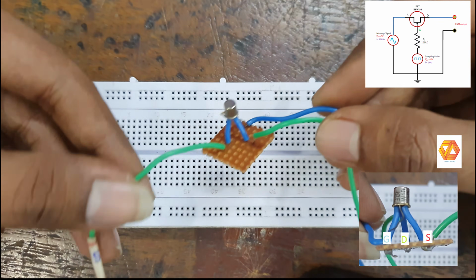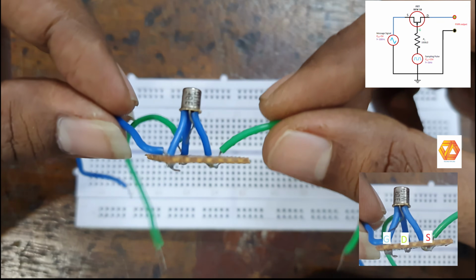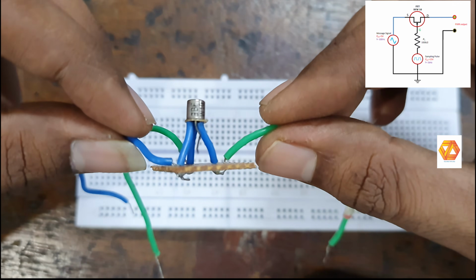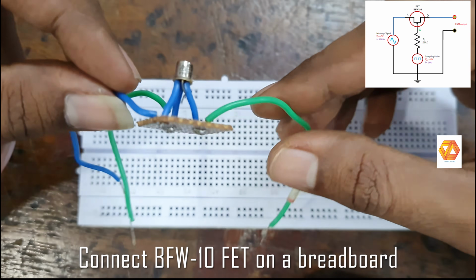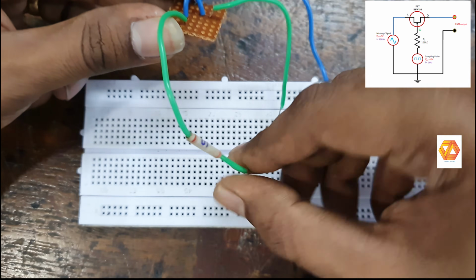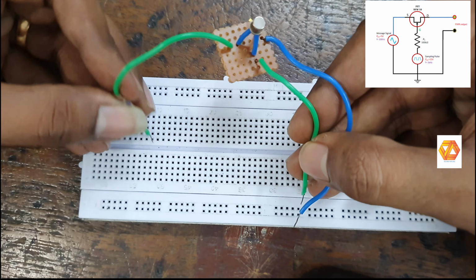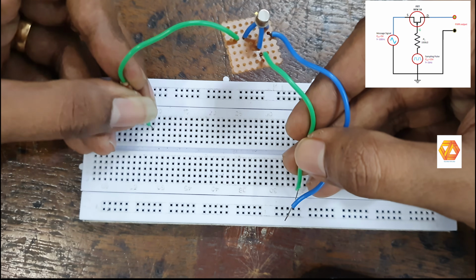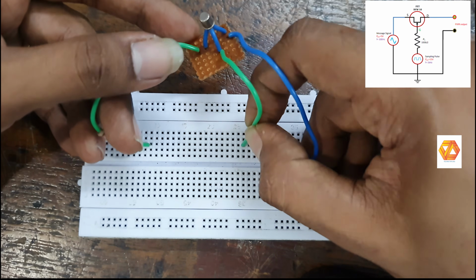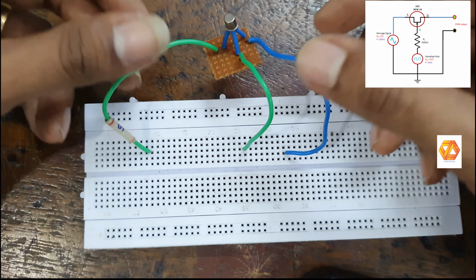So first we have to connect the BFW 10 FET on a breadboard. It has 4 terminals: source, drain and gate, and a shield or body terminal is also available. Here we are using only 3 terminals: source, drain and gate. We are not using the body or shield terminal. First connect the source terminal, then drain and gate on a breadboard. Then connect a 100 kilo ohm resistor to the gate terminal.